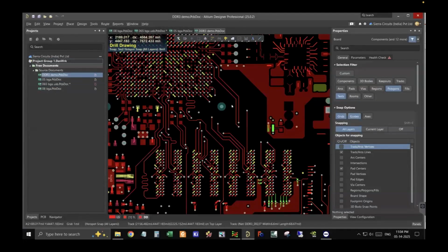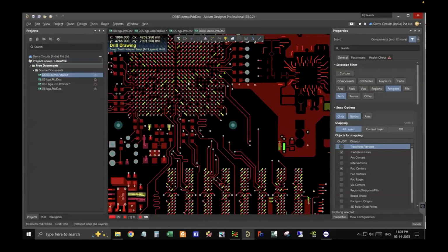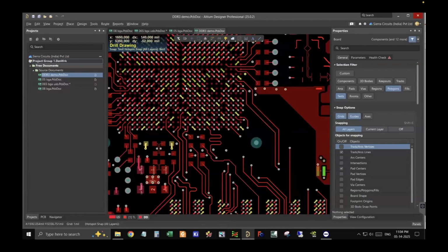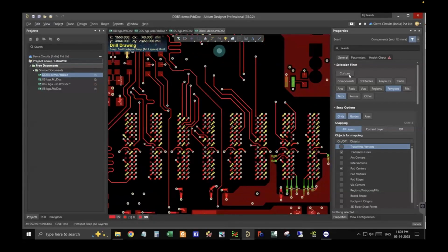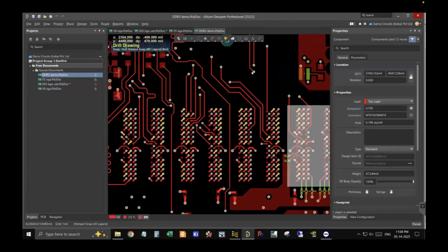Yeah, so we work with different types of high-end, high-frequency projects. One of them is this over here, which involves an FPGA. This is an FPGA with a 1 mm pitch BGA, and there are four DDRs over here. These are the four DDRs, 1, 2, 3, 4. This is a 0.8 mm pitch BGA.